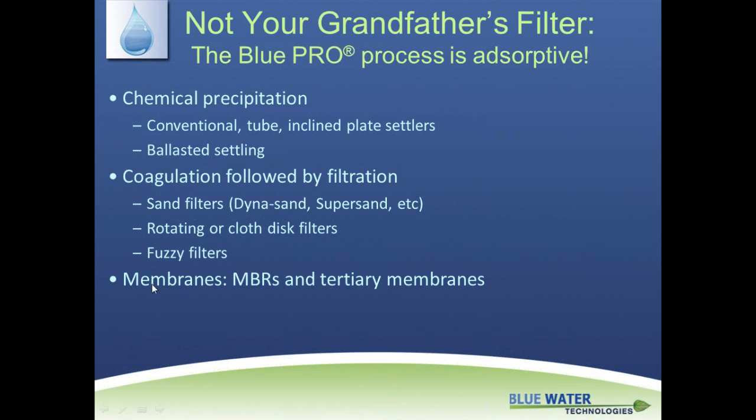And really the theory or the methodology of process for membranes is the same as coagulation filtration. You're adding chemistry up front, and you're trying to form a larger particle that physically will not fit through the membrane openings. And so, again, it's a sustainability problem, a very costly sustainability problem, because membranes are not cheap, and they're not cheap to replace.